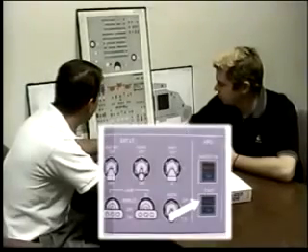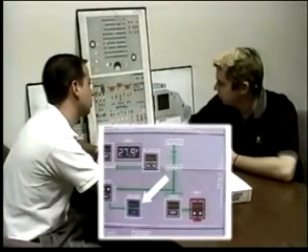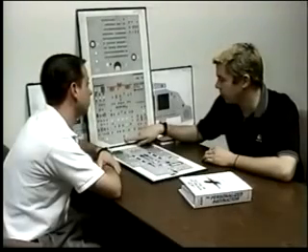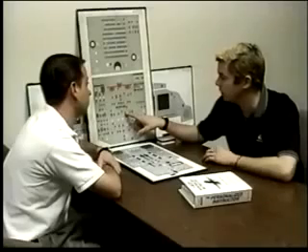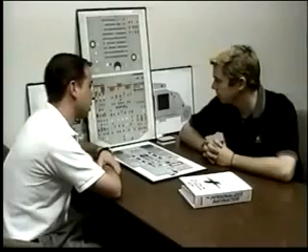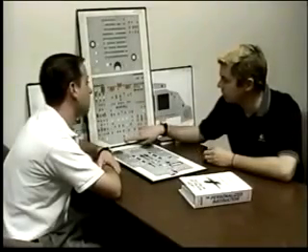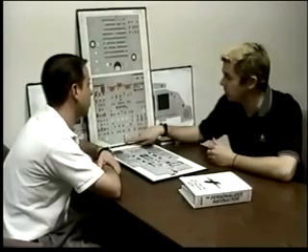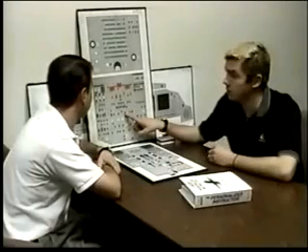How does this avail light differ from the avail light that you find on the external power switch? Well, the avail light down here just means that either electrics or pneumatics are available. Up here means that electrical power, external power is available, and it's good power to be taken on ship. So what's supplying the electrical power in this case? If I see avail and avail, then I know that the APU is supplying power, because the on light down here just means that the APU is starting, so it should be out. The on light up here indicates that the external power is on.